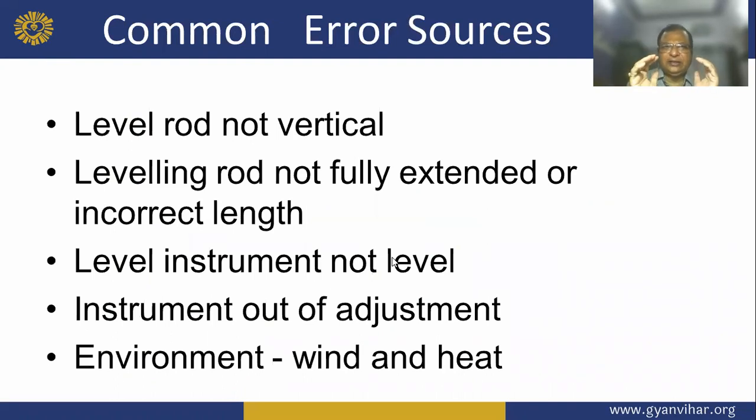Common errors: level rod not vertical, level rod not fully extended or incorrect length, level instrument not level, instrument out of adjustment, and environment, wind and heat. These are common errors.